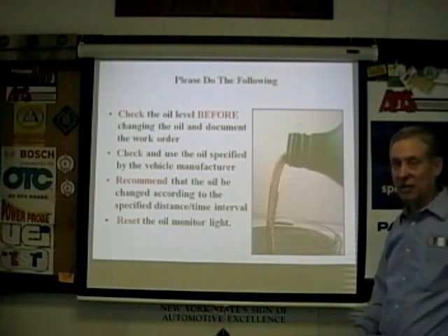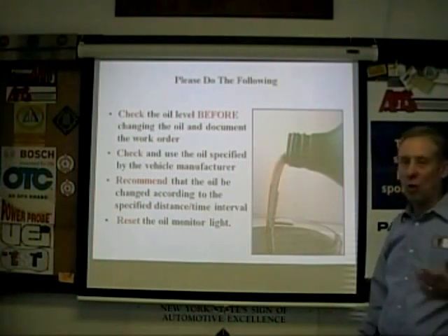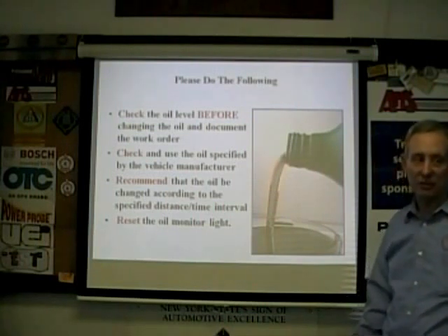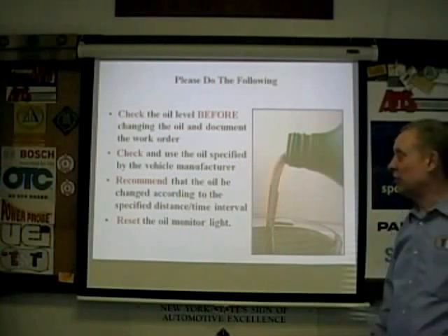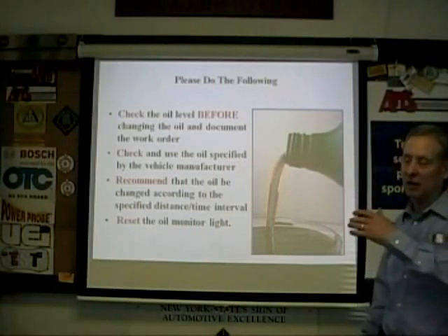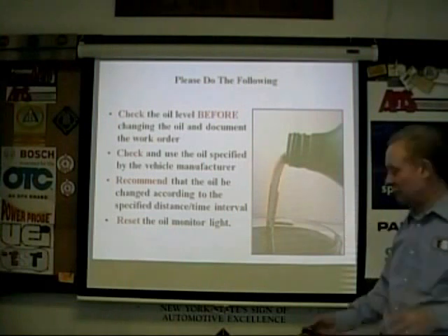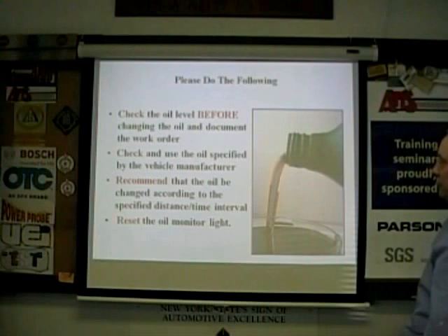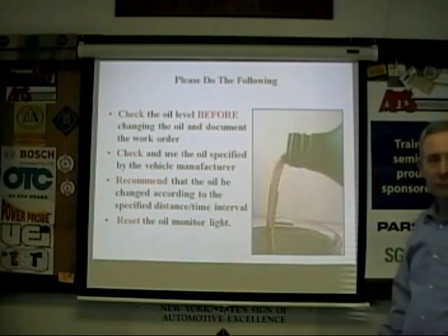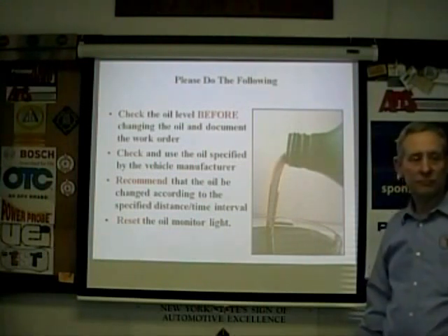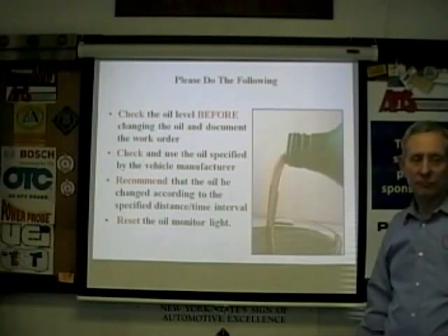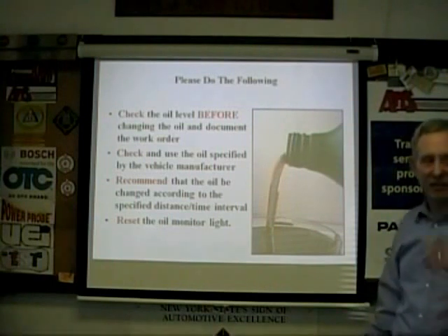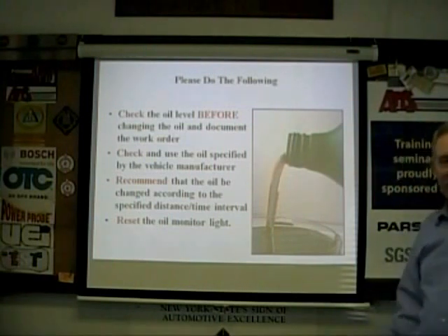However, with testing oils, one test is not generally all that. If you're really concerned about the life of your engine, unless it's a catastrophic failure, generally you have to test a sequence to get an idea of a wear pattern. The city down where I work has a special machine, thousands of dollars, that you can take a sample off the dipstick and it tells you the viscosity and what type of wear there is in the engine. But it's a very expensive machine, and I don't know anybody in the repair industry that has one. So you have to send it to a lab.